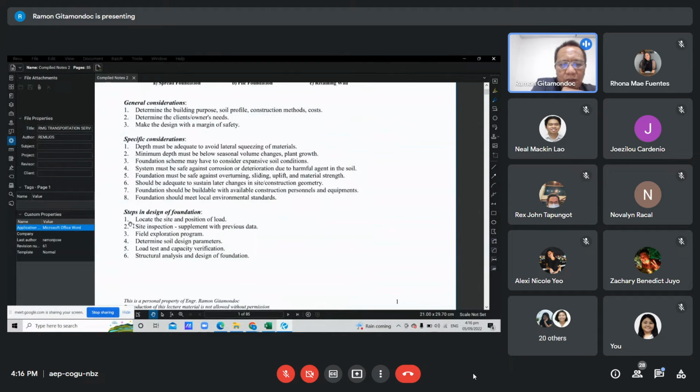A vertical load is applied to the pile, then the settlement of the pile is measured. From that, we can determine whether the capacity at the computed pile length is sufficient or not. If it is too much, then we can decrease the pile length.